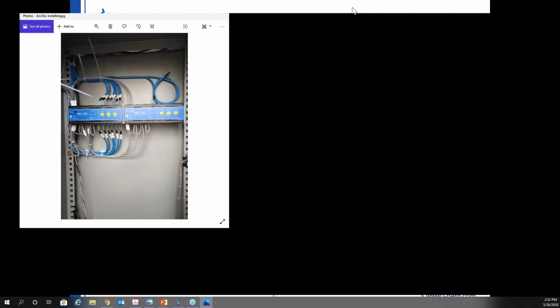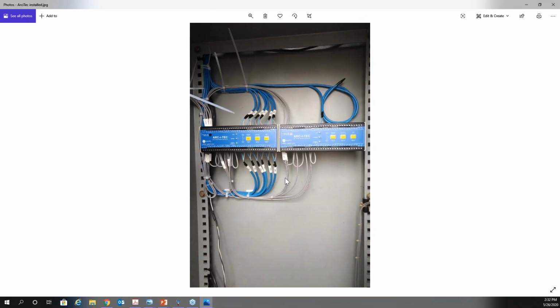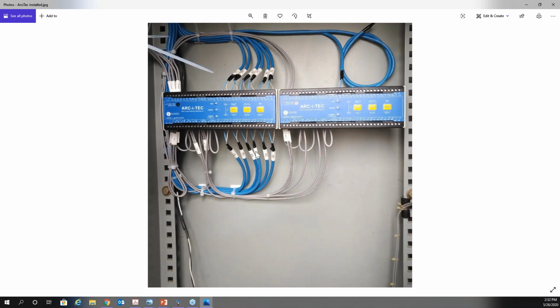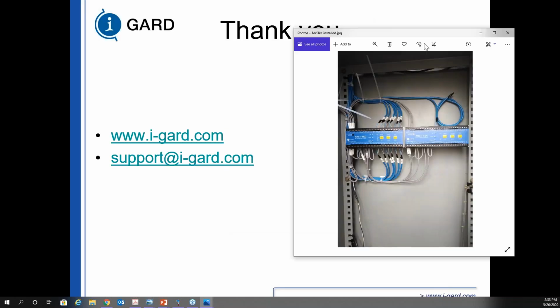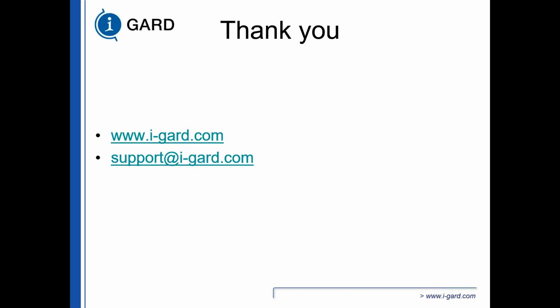And here's an example of the architect being used with 12 point sensors and a point sensor going to a fiber sensor. So these were protecting a massive transformer, rectifier transformer, and we opened up the primary breaker when that happened. So because it was a rectifier transformer, it was difficult to use light and current, so we had to use light only.